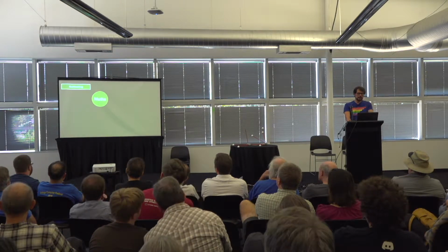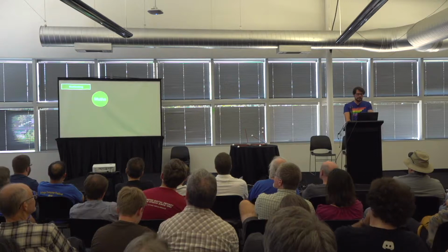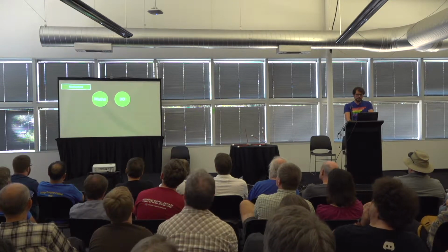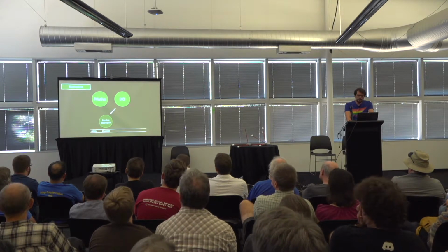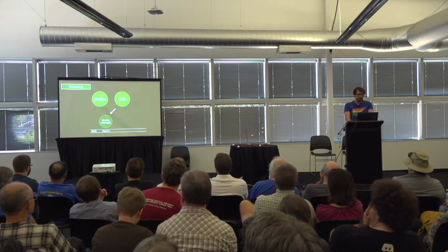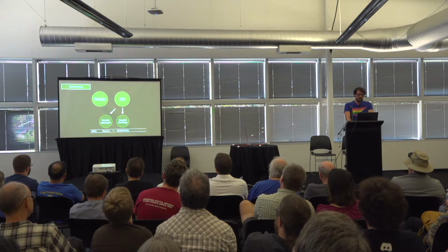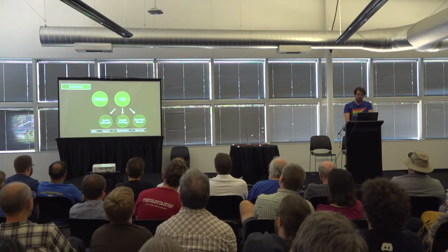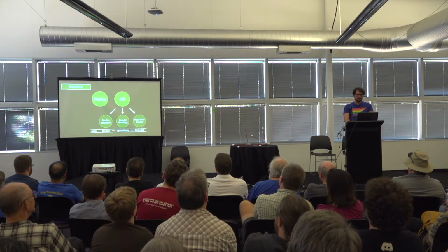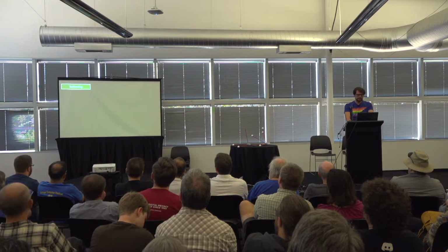The AGC has many things to do. It does mathematical calculations that can take several seconds, and it does I/O with its devices. It services interrupts when the device wants the computer's attention. A simple example would be a key press on the DSKY. It does regular servicing of devices, like updating the display, and it supports real-time control, like flashing a lamp or firing boosters at exactly the right time. There's only a single CPU, so it must switch between the different tasks.